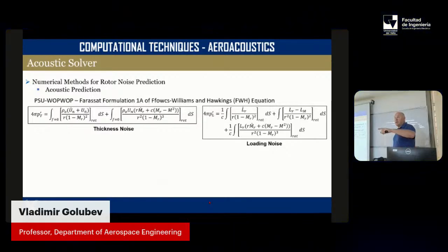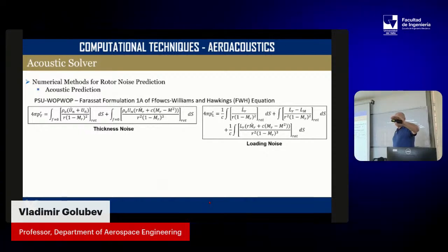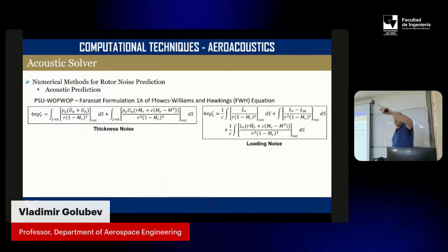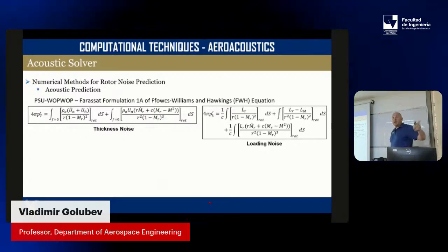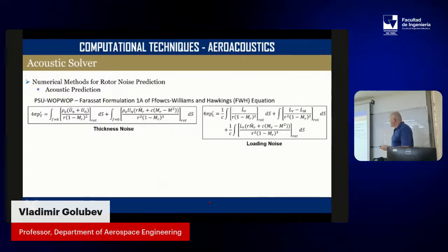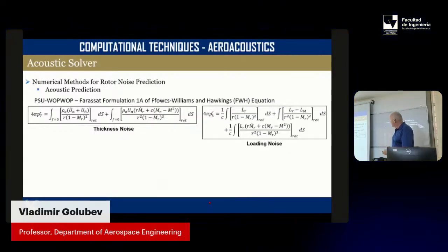So if you have the near field, it could be the surface of the blade with an unsteady pressure on it, which you take as an input, or you have a control surface around it, which will account for the turbulence in the near field, which is a wake, for instance. That will contain more terms.